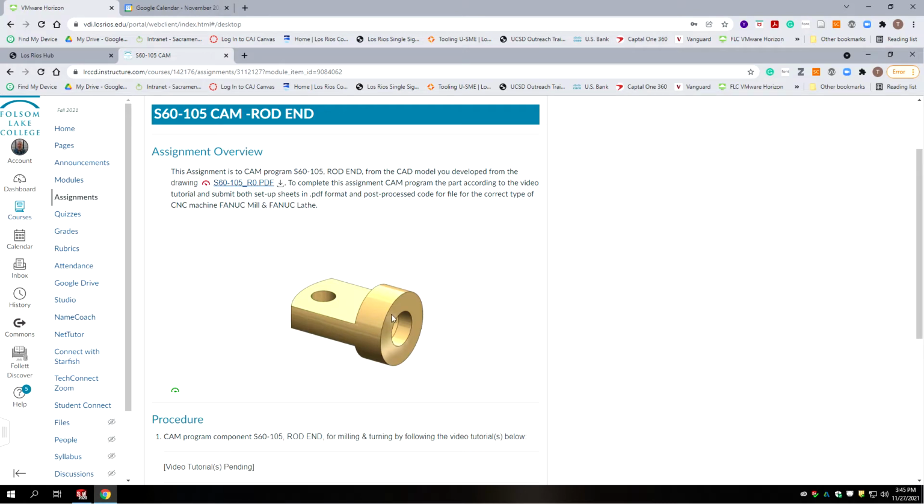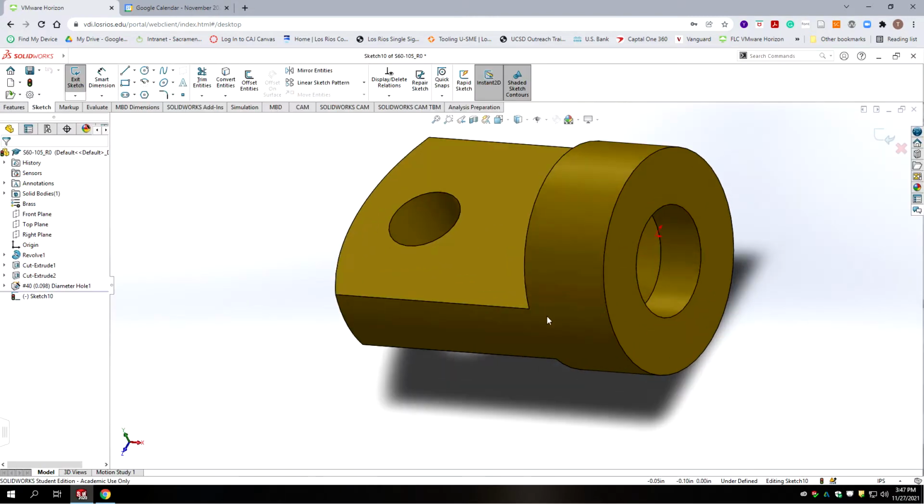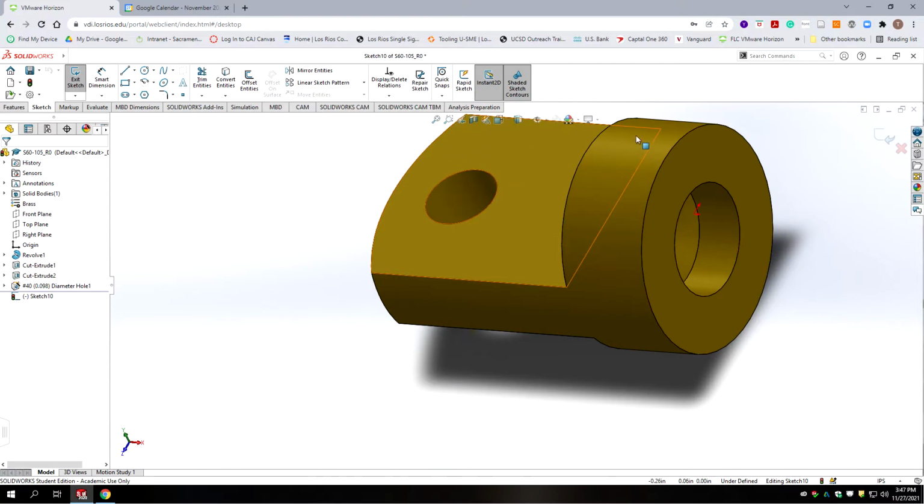Okay, so this is a turned end milled part. We're going to turn the outside profiles and then do the drilling and the flats. Now, when we modeled this, I led you astray and we revolved this component. But if you actually look at the drawing, the very end here, the way we model it, is spherical. So what we're going to end up doing is turn the outside of the part, but this radius side will be just created by our profiling.